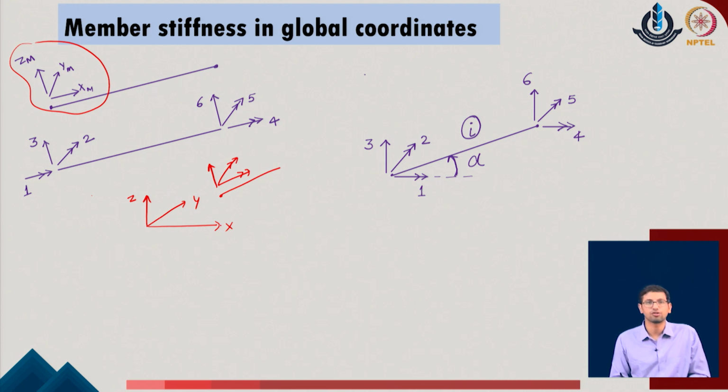So, these were the 3 degrees of freedom which were located in the plane of the grid, now in the local member coordinate. Now, if I just want to convert it in the global coordinate, I realize that this is the first one which is along the direction x, second one the moment about the axis y, this is second, and the third one which is the direction normal to the z, and that happens to be the same in the given system, right.